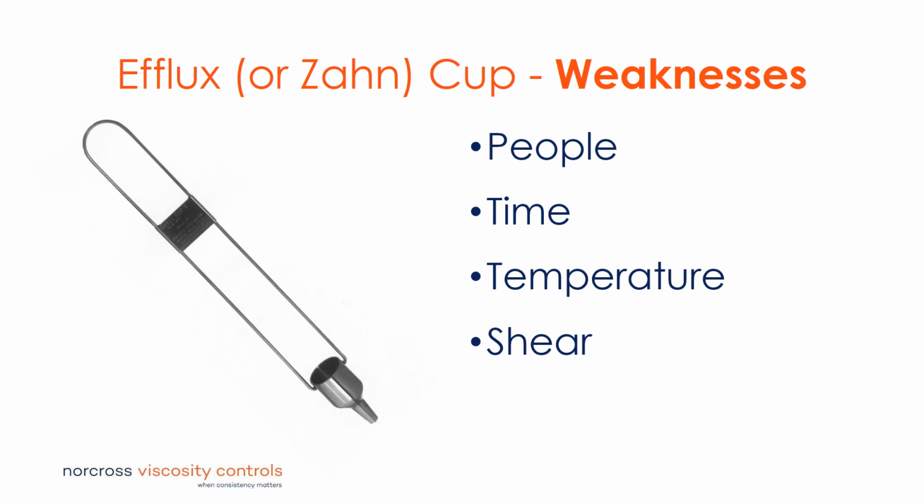Then there's shear. Most common process fluids, inks included, are non-Newtonian, which means they experience shear thinning. A simple explanation of shear thinning is that certain fluids that are thick or viscous under static conditions will thin or become less viscous when shaken, agitated, or otherwise stressed. Inks are highly viscous under normal conditions, but will gradually become less viscous as force or stress is applied. Removing ink from the process eliminates the effects of process shear. This ultimately ensures that you will not get an accurate process reading.